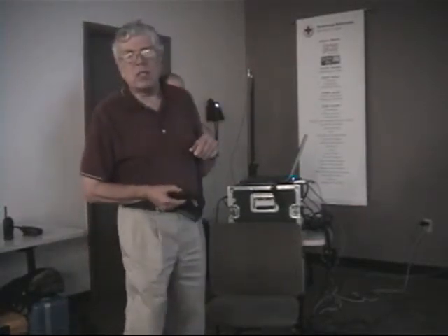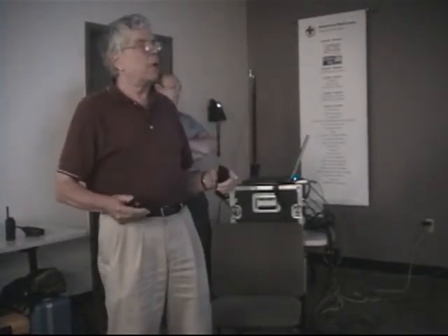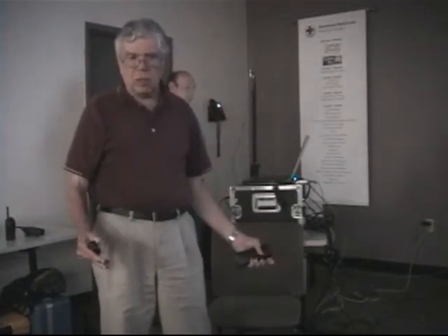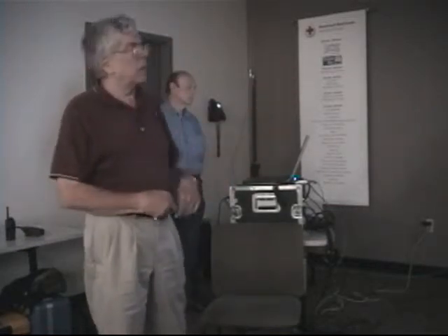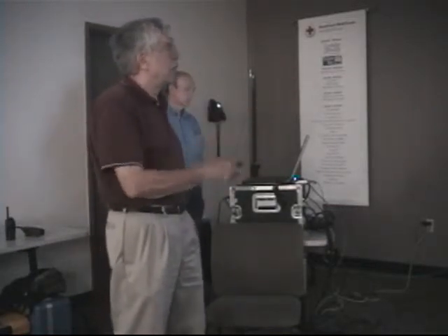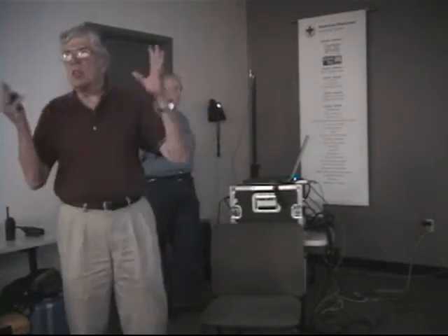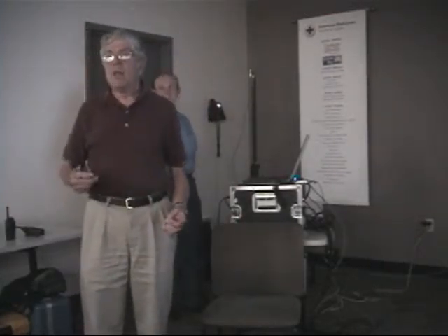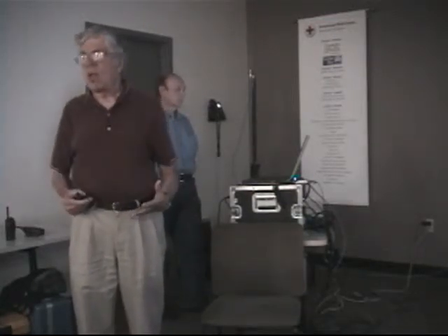SINAD and bit error rate, those are static tests. We set up a radio on a bench with a piece of equipment, a signal generator, service monitor, and static is not, that's a closed system. It's not subjected to any disruptions. But the real world doesn't work that way. The real world has noise and interference and multipath and fading, and picket fencing is what we call that. Anybody that's ever used a two-way radio in a vehicle, you've heard that.